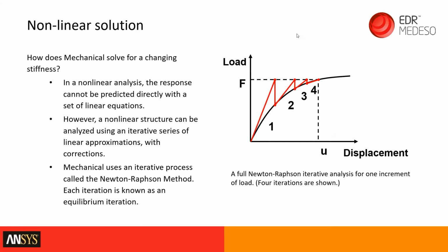It'll calculate a force displacement. It will look at the external forces in the structure and the internal forces in the structure, and see if they're in balance. If they're not in balance, it'll do another iteration, until the external forces and internal forces are in balance, and we say the structure is in equilibrium.